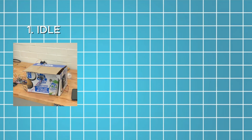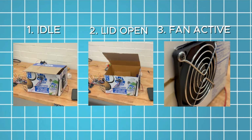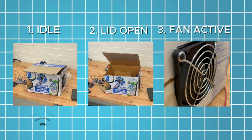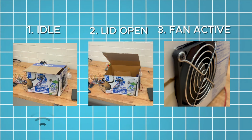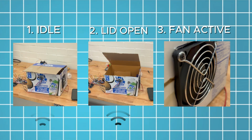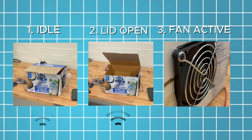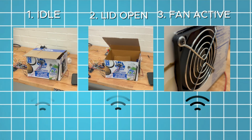The system has 3 primary states: idle, lid open, and fan active. In idle, the sensors are being sampled but no actuation actually occurs. When the ultrasonic sensor detects proximity, the servo motor opens the lid, transitioning to the lid open state. If humidity then exceeds the set point, the fan turns on via the H-bridge, entering the fan active state. The system returns to idle once the conditions normalize again.